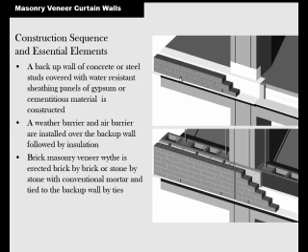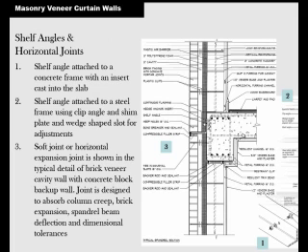Here you can see how it's built up. This is your flashing that comes down, and then your masonry is on top of that. There's your weep holes that we've talked about before. And then they'll have a glazing system wherever that needs to start. Here's a good detail for you to study, perhaps copy for extra credit, of a masonry veneer system.